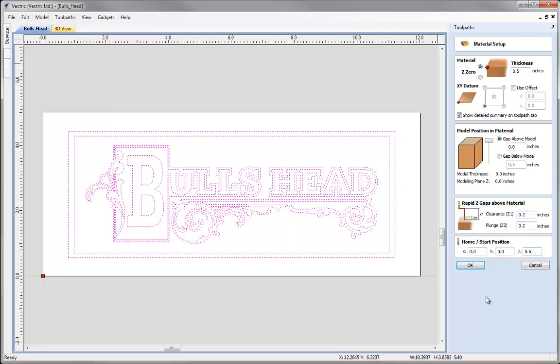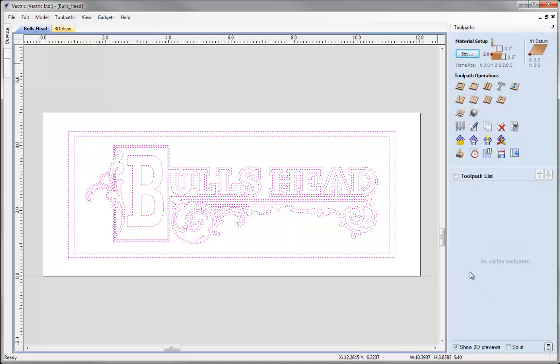If everything in there looks correct, and you should always double check this, then you can hit OK, and now we're ready to choose the toolpath type that we'd like for this particular job. Before we do that though, I should mention that it's very important that if you plan to cut this part yourself, in order to test the software with your CNC, that you ensure that the values you enter for the toolpath and the tooling are safe and appropriate for what you have available, the material you're planning to cut, and the way that your machine operates. So the toolpath we're going to use for this is a VCarve Toolpath.